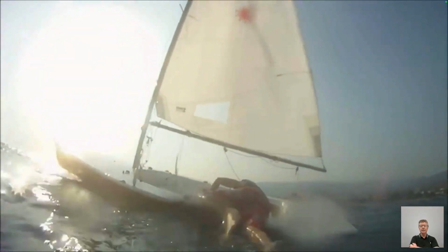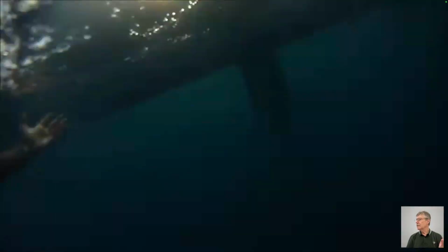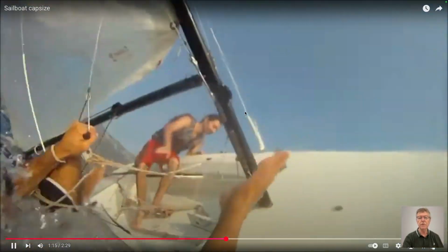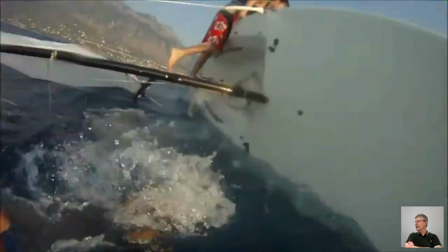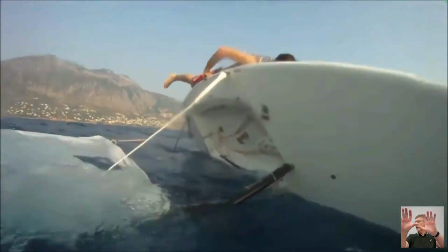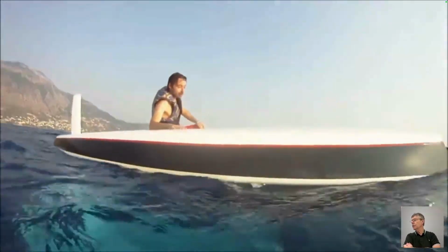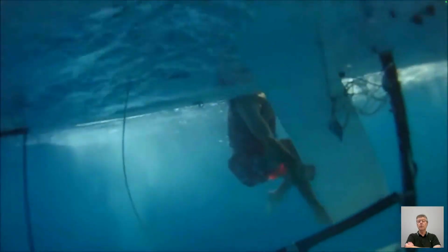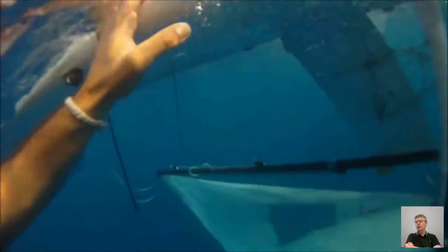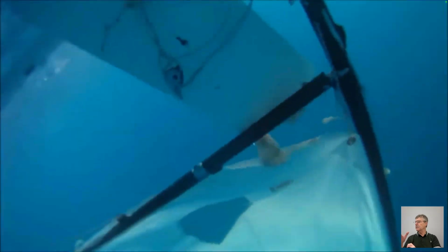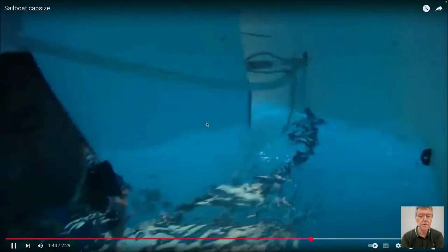And so I guess, what is this? Is this a laser? I didn't see the thing on the... Yeah, it's a laser. So the kind of concepts that we've been talking about. So you know what the force would be on the sail. It would be kind of a set force of the wind having its velocity broken and v squared over 2g being turned into p over unit weight. We'll talk about Bernoulli beginning in week 4, next week, I guess, a week today. But the forces acting on the dagger board, even though it's moving, we could ignore that, would be this prismatic distribution, triangular distribution, getting larger with depth.